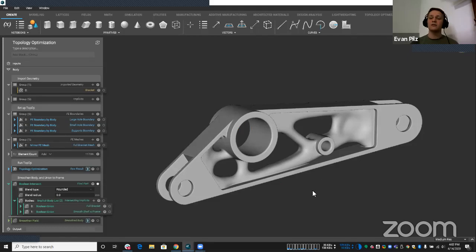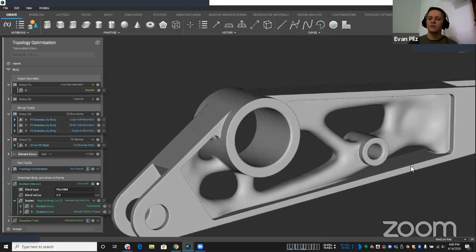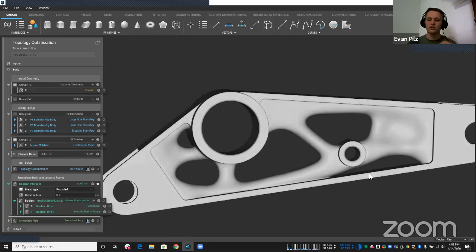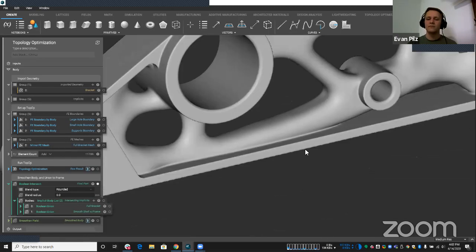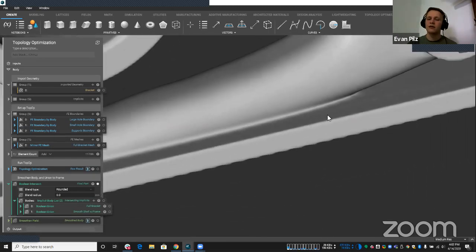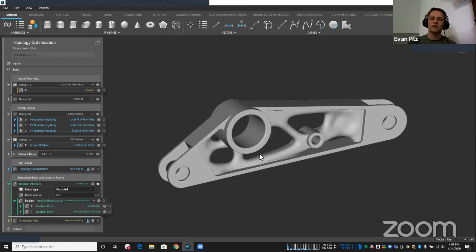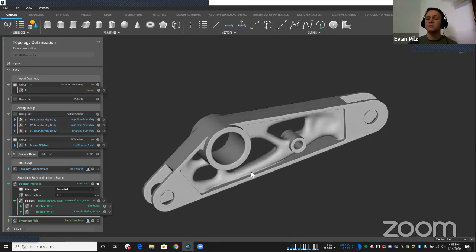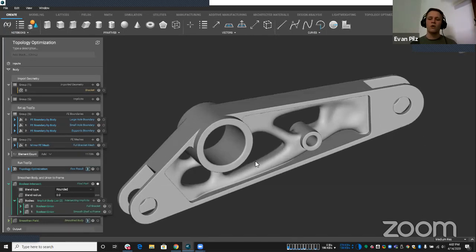It takes about 2 minutes to do, so there's no real need to create a passive region when you can just put exactly what you want back right away, and not have to worry about smoothing out the regions that might be left over from the optimization. It's back, it's crisp, it's clean, and it's good to go. And you can, again, control those fillet radii just to avoid any extra stress concentrations. So inside of the topology optimization realm, we offer quite a lot of power and a lot of control over what you're doing and your results there. I hope that answered your question.